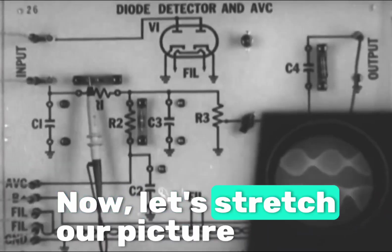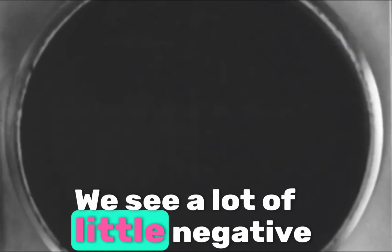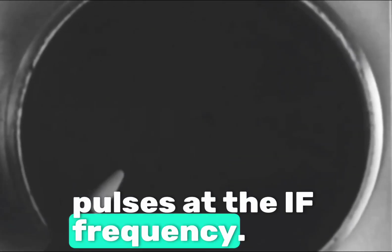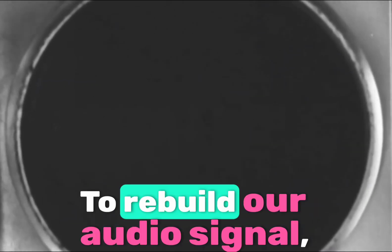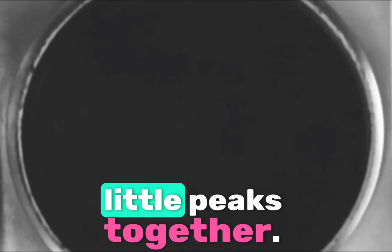Now, let's stretch our picture sideways and get a really good look at what's there. We see a lot of little negative pulses at the IF frequency. The audio signal isn't really there at all. To rebuild our audio signal, what we must do is join all these little peaks together.